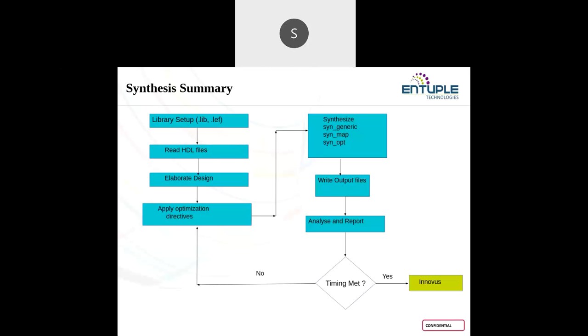Actually, I am not familiar with the term path histogram, but for whatever timing paths are there in the design, for each and every path we can see the histogram, the graphical, pictorial representation of each path. You can see that from the timing debugger window.